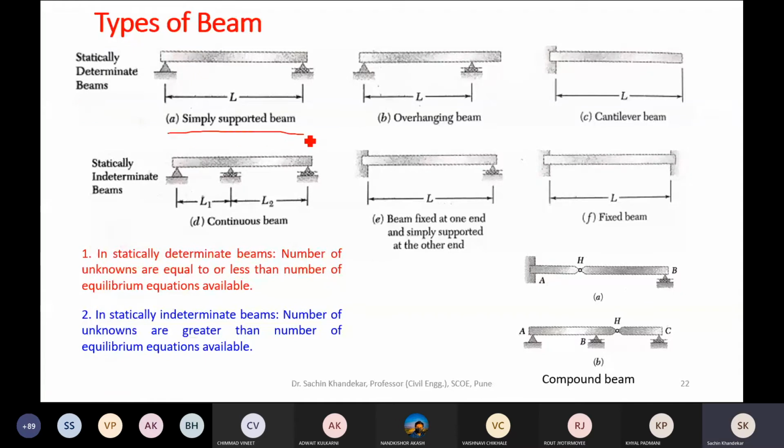Okay, fine. Coming back. Simply supported beam. Usually in case of a simply supported beam, one end is a hinged one and the other end is a roller one. On the other hand, suppose both the ends are rollers. When the brakes are applied by the driver onto the vehicle, a horizontal force may be developed, either leftward or rightward, and because both these supports are rollers, the beam may move in a forward or backward direction, something like this. Which must be avoided, right?